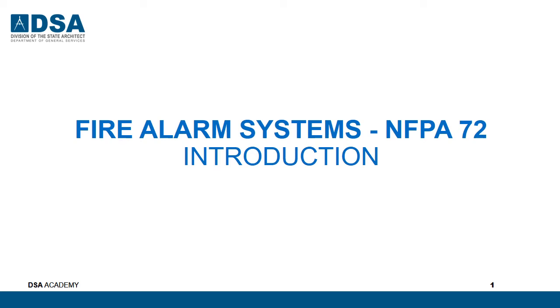Let's move on to fire alarm systems. Fire alarm systems are required per the Building and Fire Code and are to be designed and installed in accordance with NFPA 72 as amended in Chapter 35 of the Building Code. The present Model Code edition of 72 is the 2016 edition.